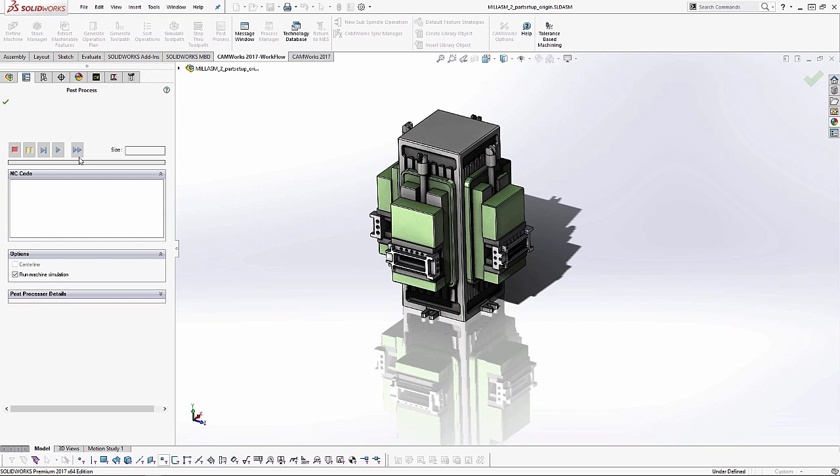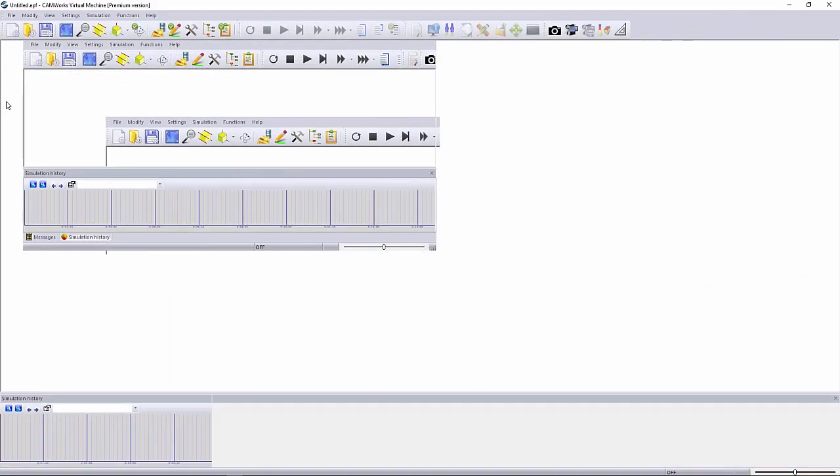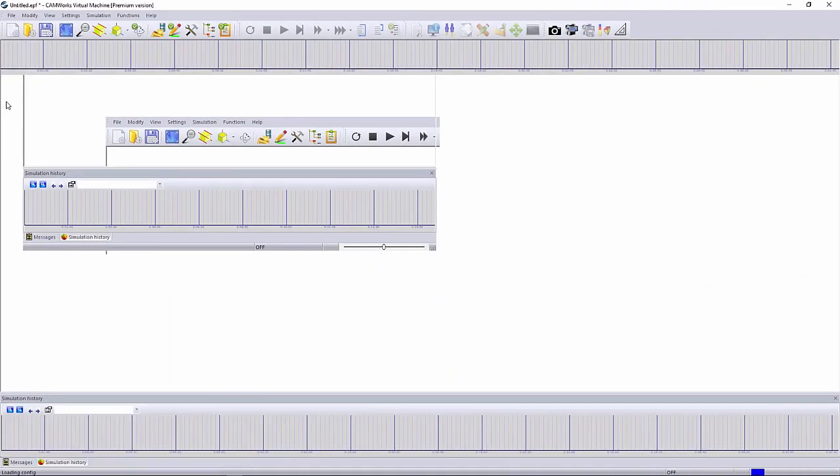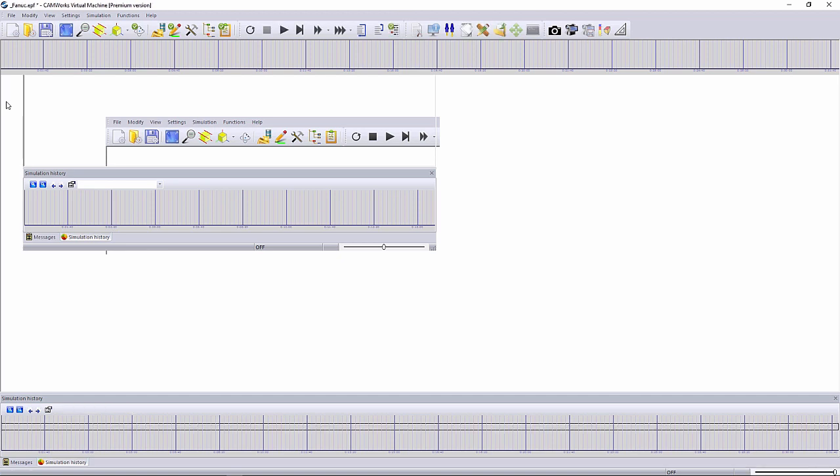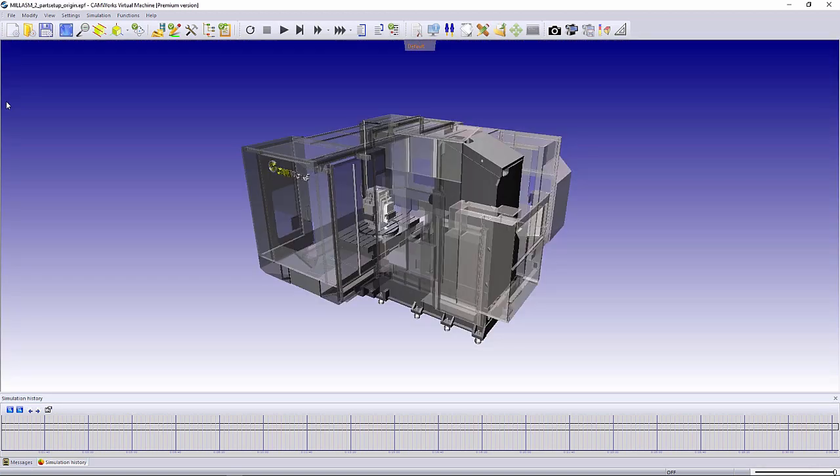The nice thing here is that I'm going back and forth in the virtual world, and I can do it within seconds. What I'm not doing is generating a Gcode file, throwing it on a USB stick, walking over to my mill, loading the file, adjusting the Z offset so I'm running dry over the air, and watching it move in person. I'm not losing any accuracy, but I'm saving a lot of time.